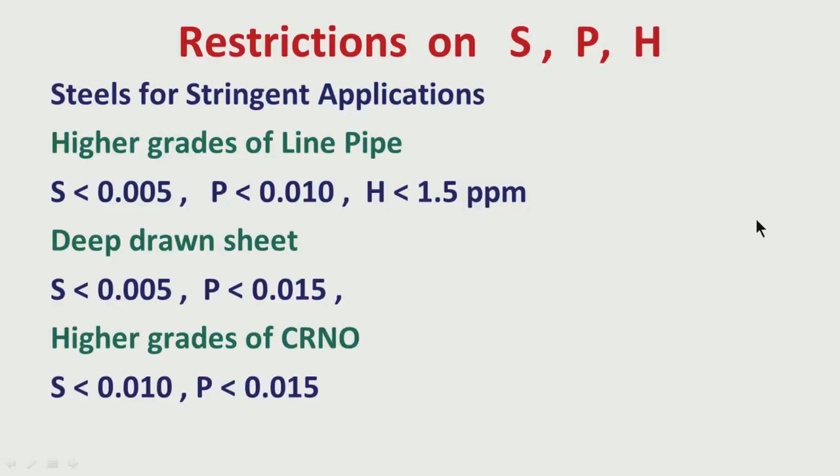So, for hydrogen analysis, what is important is you put the sample under liquid nitrogen and then take it to the hydrogen analyzer. That will give us a more realistic analysis. We should get a realistic analysis only when the sample with hydrogen is kept in liquid nitrogen before it is put to the hydrogen analyzer.